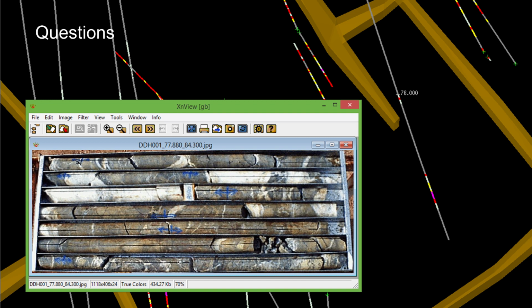The only thing that was a little bit different that would require the Geotech module was when I had the oriented drill core and I was rotating it around, and then I digitized that structure. Digitizing that structure into the Geotech database requires that Geotech module. There's a whole lot of other functionality that's relevant in terms of stereonets, rose diagrams, tadpole plots, etc. in that, which I haven't expanded upon. Could be a topic for another webinar. But yeah, just the Vulcan Geomodeler plus the Geotech toolbox just for that one item.